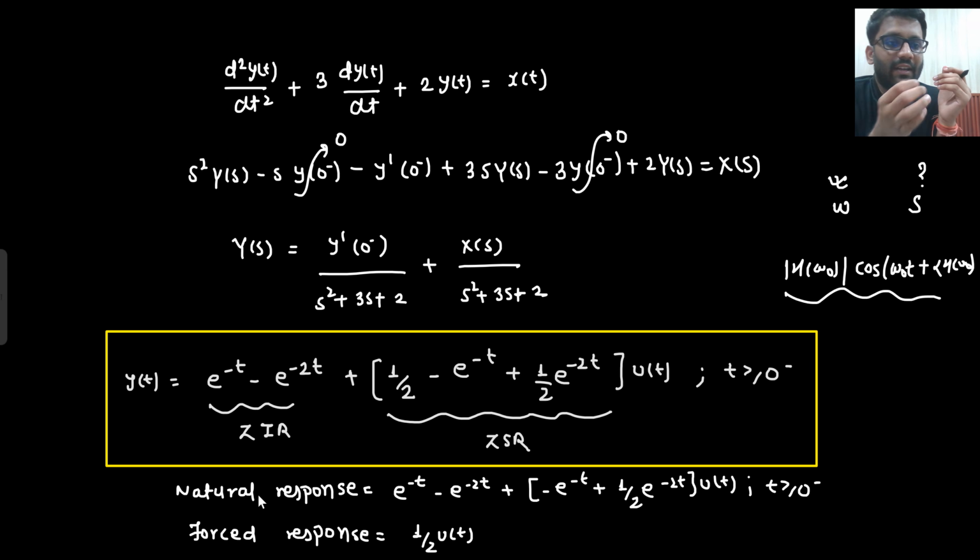That was the necessity that you need to introduce another sigma. Initially you have X of omega versus omega. Now you have to introduce another sigma, that's sigma where the ROC is defined, the real part of S. You have to introduce that real part of S just because of this fact. Is that clear to you?